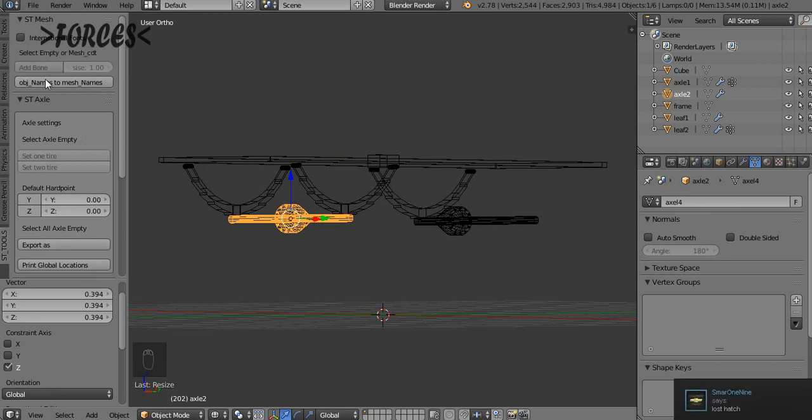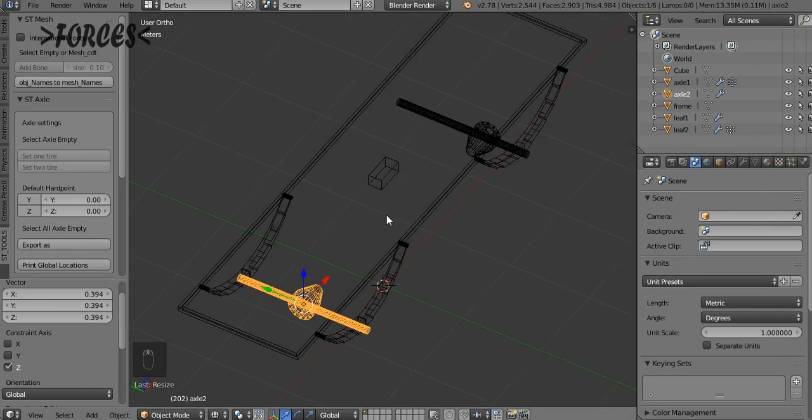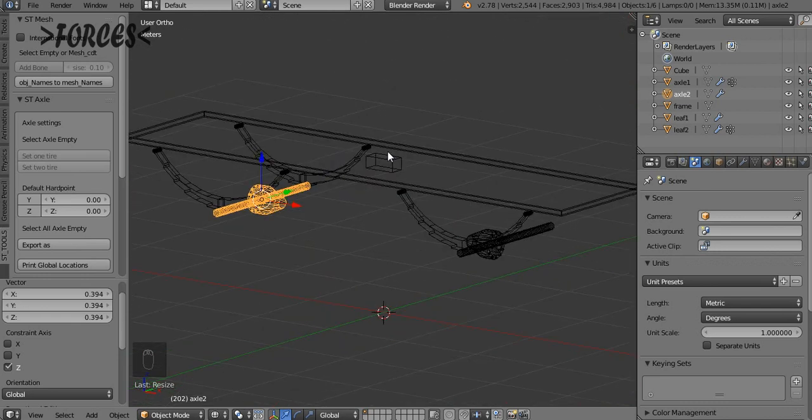International fonts, don't activate this. Most of the time it makes Blender crash, and some users will see it like this, in this tone. Okay, this adds a bone. Let's put this to 0.1 because it's a 1 meter bone, and let's change our units to metric. Okay, always remember to save. We don't want to lose our project, right?